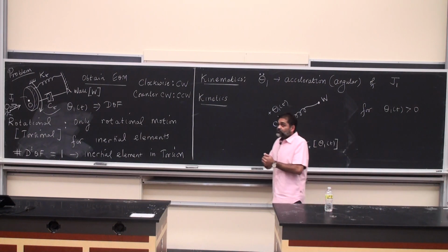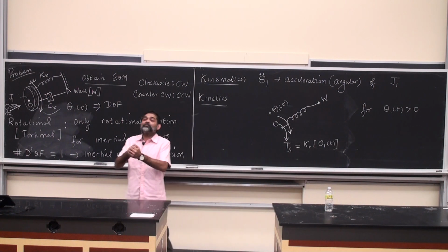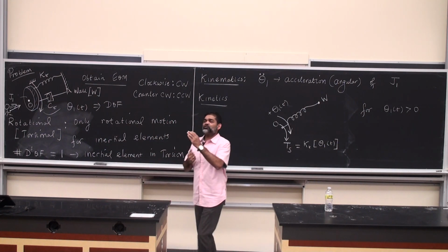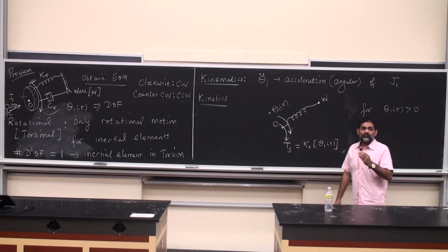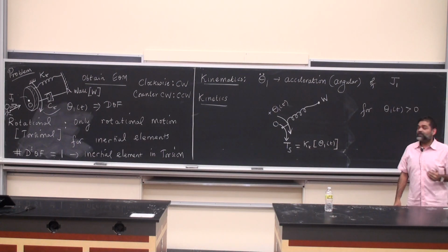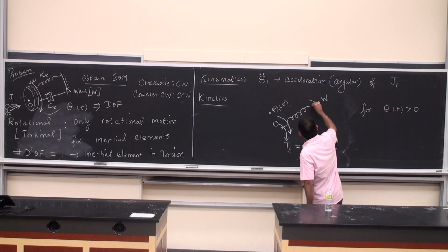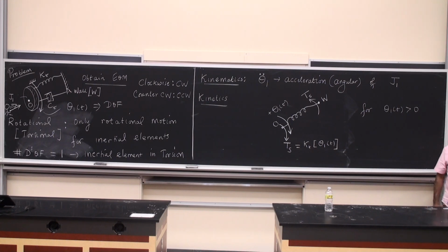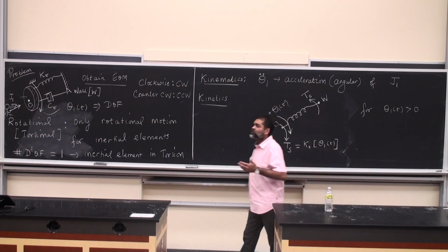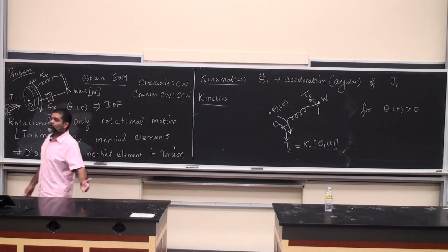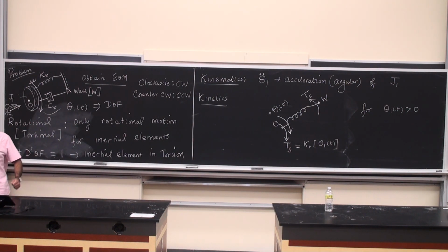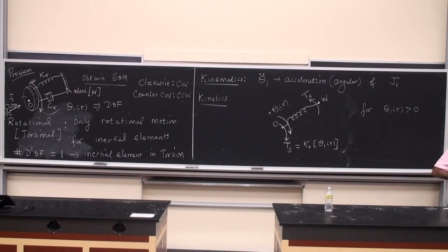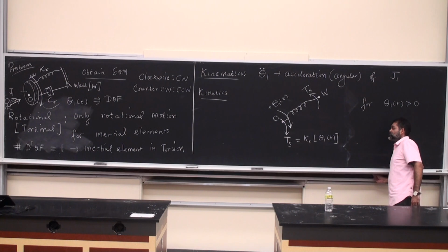But the figure is not done. Every body, every spring, every damper needs to be in static equilibrium, because we ignore the inertia of the spring and damping elements, which means that on the other side of the spring, I need to have an equal and opposite torque. Does this make sense to everybody? Common sense, right? Everything has to be in static equilibrium. If I choose one way on one side, it has to be the other way on the other side. No tricks, no fooling around. So this is the situation here, and I can do the same thing for the torsional damper as well.